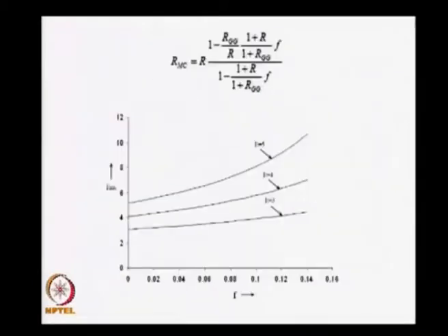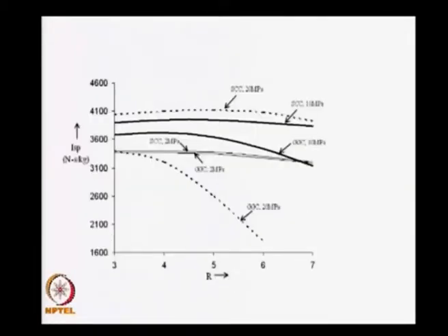We go back, we said this is the fraction I have calculated, I come back to this a little later. All I am saying is, if I operate a gas generator cycle at a small value of pressure, this is the net value of specific impulse I get. If I operate the same engine on a staged combustion cycle at low pressure, I get a slightly better performance because I have not lost very much because F is still small. I still find the gas generator cycle is lower than the staged combustion cycle, but the loss is small. The loss is small because F might be something like 0.01 or something. If I go to slightly higher pressure, what do I find?